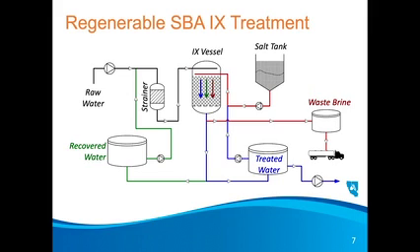So here's a schematic of what we refer to as the strong base anion exchange resin process, I should say. This is very much similar to what you use for nitrate treatment. And so we have raw water coming in. You may go through a strainer to remove suspended material to protect the resin. Then you go through a resin process, and coming out, you go into a treated water tank, and I'm not listing the chlorine here for disinfection, but that's a different issue.